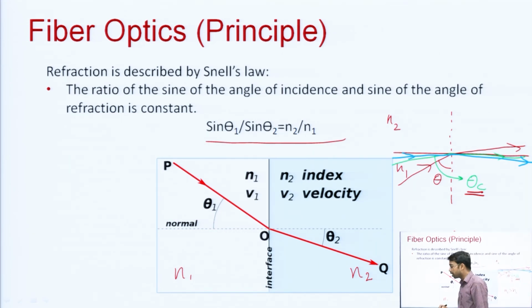So, in blue color, this is a light ray coming on this surface at an angle greater than the critical angle. Because this angle is greater than the critical angle, the light ray will be reflected from this surface. The whole light ray will come again, it will not go in the cladding. This part is also transparent, but the light will not go into the cladding, it will again come in this part, and this phenomenon is called total internal reflection.